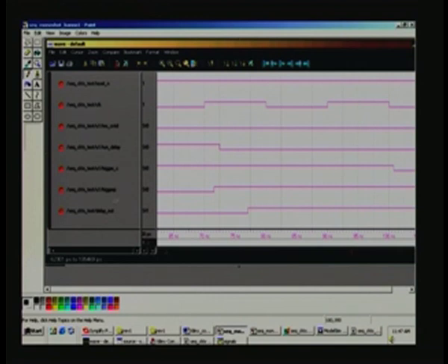This delay out is the final output. You have a trigger P, trigger C, and based upon the 0-1 condition we set another signal called run delay, which simulates the start pulse of the monoshot. So, it is high here and goes low here. When it becomes high somewhere here, probably just before, I should have captured one more on the left, but that is not a major issue. What we are concerned with is only the delay out, which is the required monoshot operation that we are looking for. So, the idea is we give a start pulse for the monoshot, and the timer runs, and it starts running right at this point.